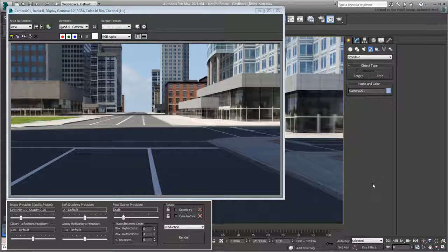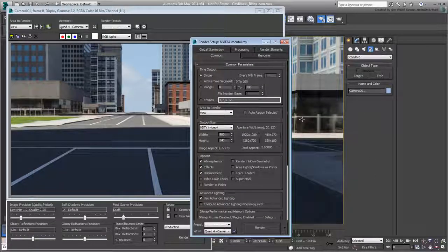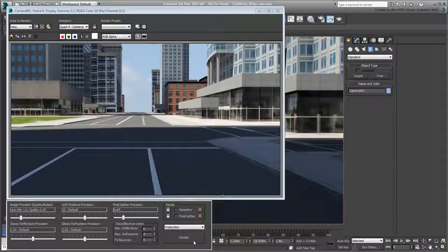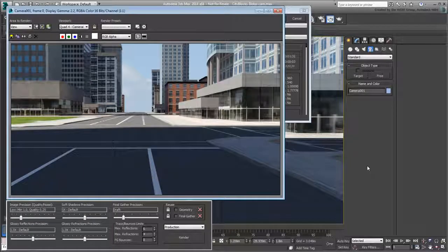This is better, although you need to change the direction of the sun in a minute. Notice that at this time, the urban design components are not shown in the render. This is understandable as they are hidden from view. You can certainly unhide them but their sheer number would certainly affect viewport performance. An alternative is to go to the Render Scene dialog and force 3ds Max to render hidden geometry. This would increase render time, more objects to render, but at least viewport performance remains unaffected.